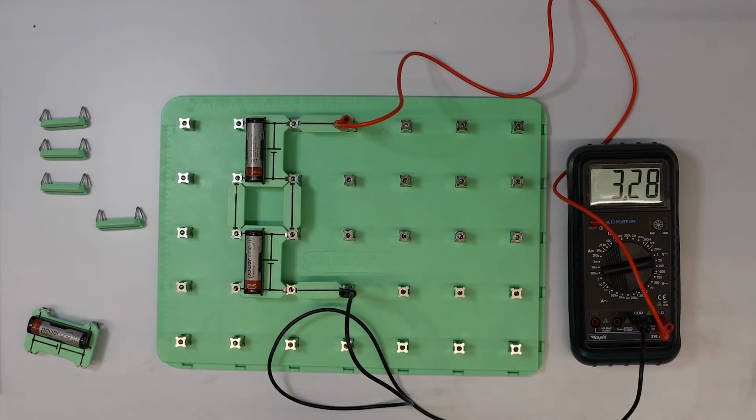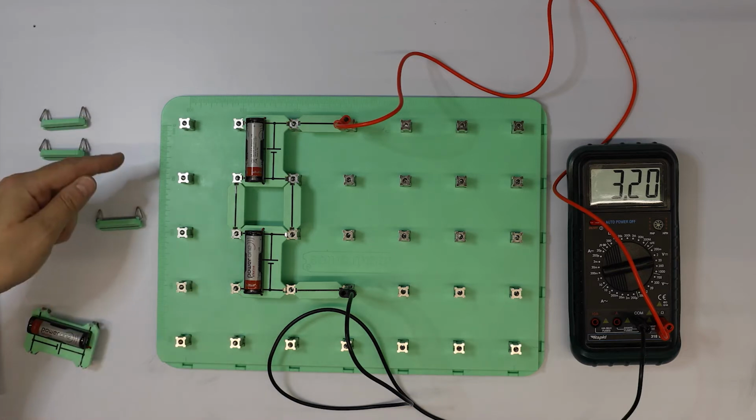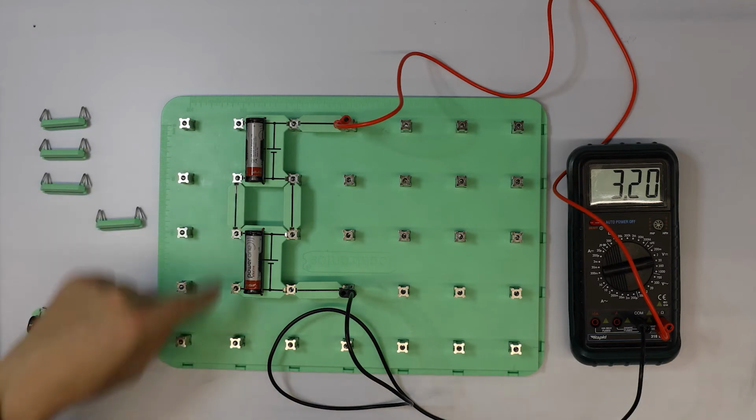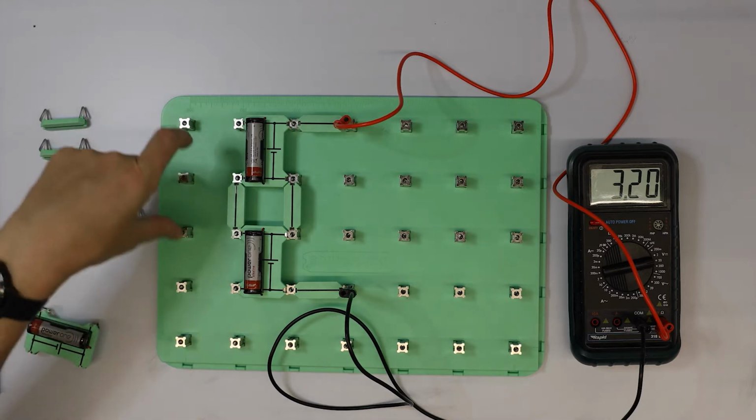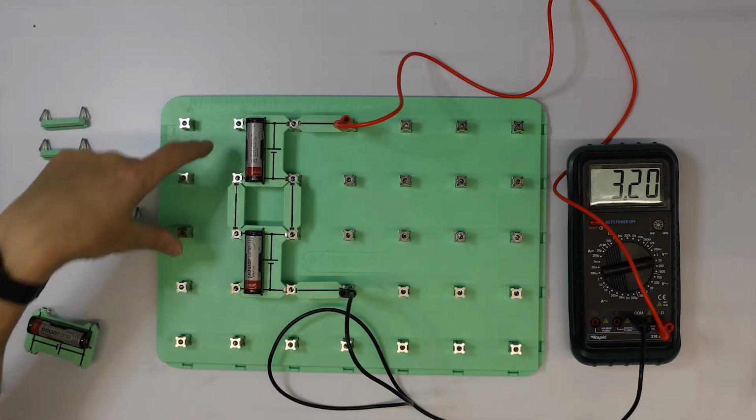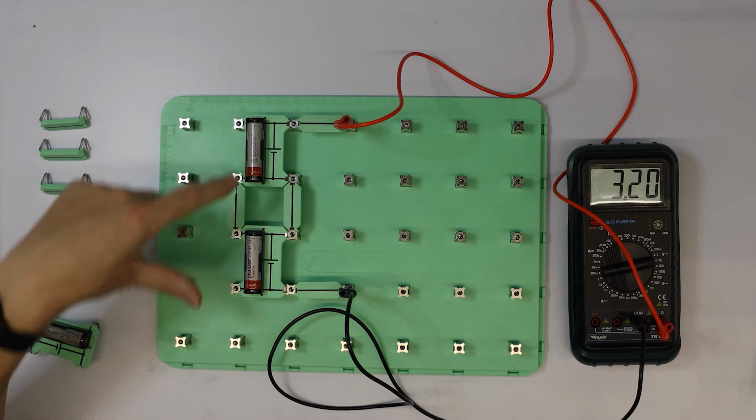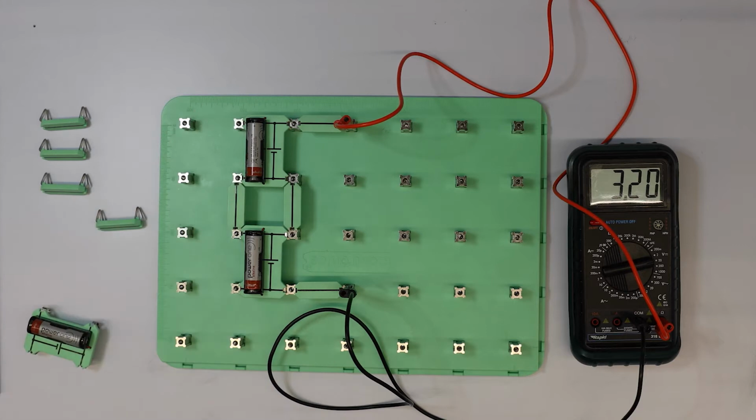And sure enough, when I do that, I'm now getting a reading. So I'm getting a reading of about 3.2 volts, which is perfect. I saw that I've got 1.6 volts across the first cell, and now here I'm reading 3.2 volts across both cells. So I would record that value for experiment B on worksheet 1. Okay, so what we've learned here is if I connect the positive terminal of one battery to the negative terminal of the other battery and then measure the voltage across the two, that's going to be the sum of those voltages.